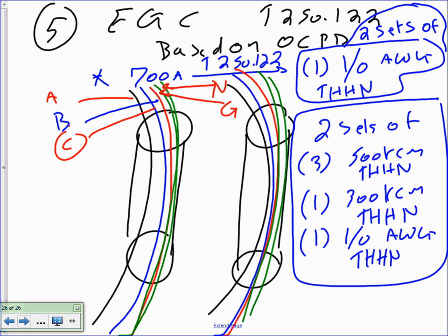Real world though, you're always going to pull it in. A lot of good engineering design, a lot of engineers don't like to depend on the conduit, especially for feeders. Branch circuit is not a big deal, but for feeders, they don't like to depend on it, so they push a ground in it. We're almost there. The last panel is going to be my equipment ground conductor.